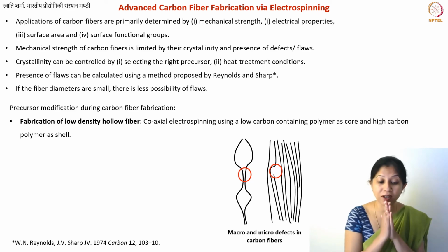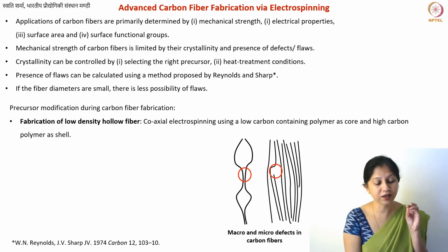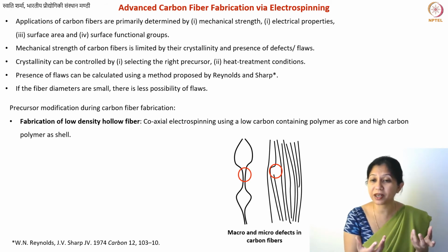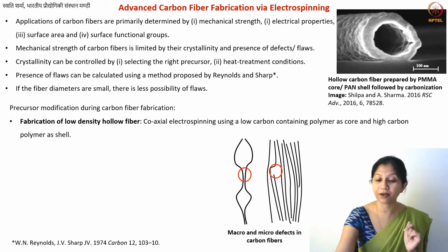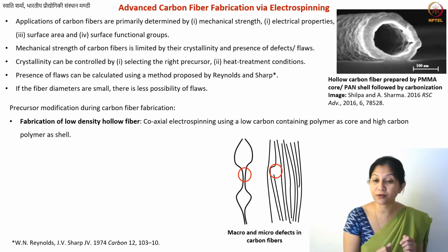What will happen once you carbonize these structures? During the heat treatment, the core material, because it does not give good carbon anyway, will disappear to a great extent, if not completely. And then your shell will remain there as a carbon fiber. In fact, these kind of experiments have been done. This is a very, very beautiful picture you see. You have a hollow carbon fiber now.